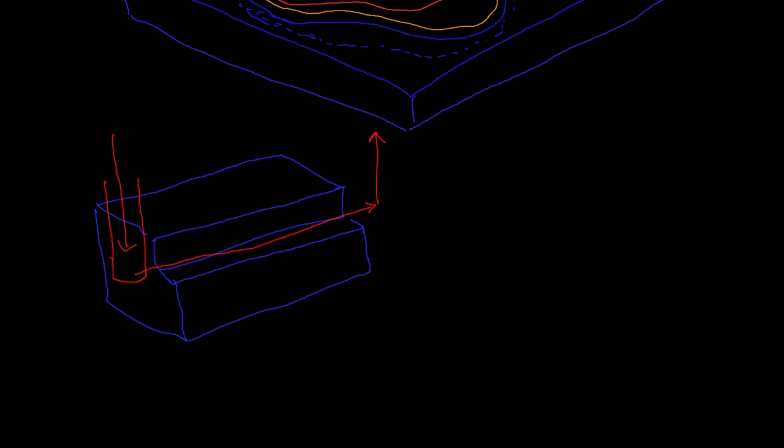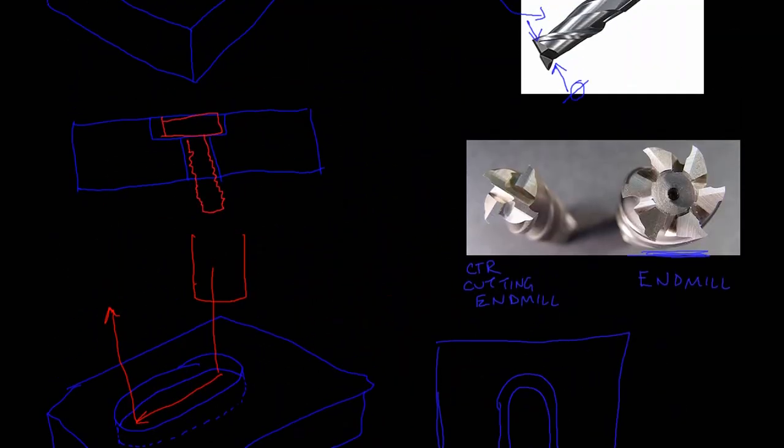Whereas the other tool, you could come in a little bit closer and cut this material as it's plunging. In this case, it doesn't really matter, but really for that pocketing function, you would not be able to use that tool. You could use the center cutting end mill.